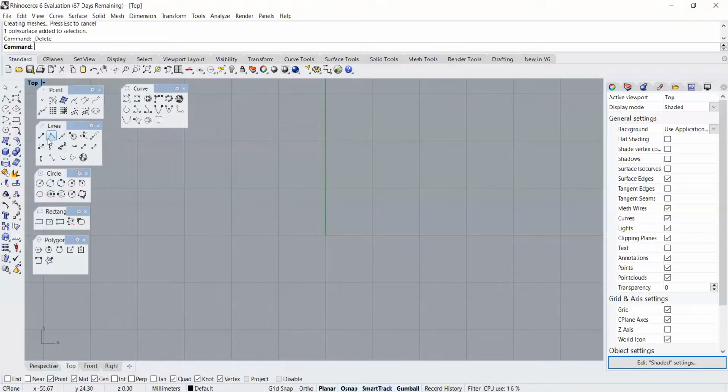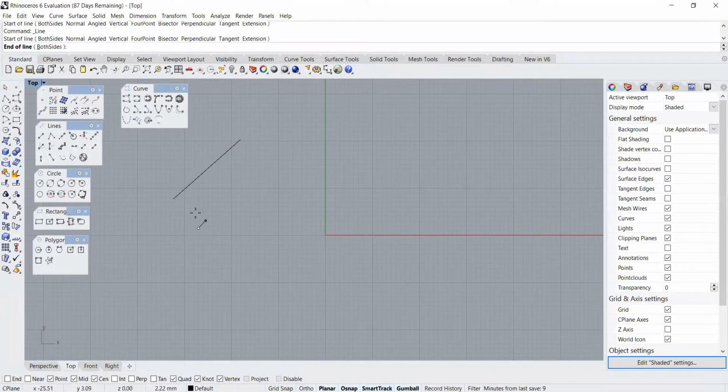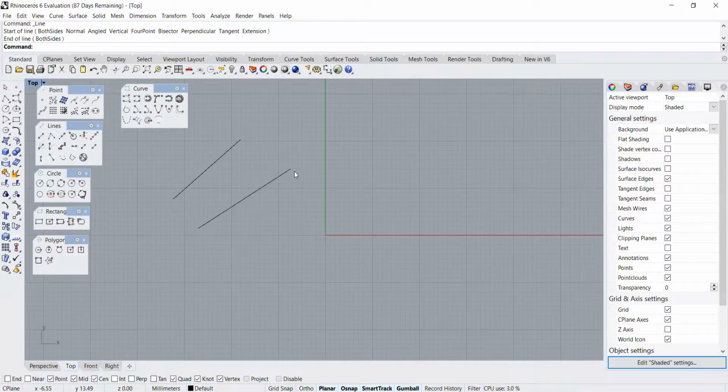So I'll try each and every one out. So it says single line. It's just a segment. So when I do first click, it says end of the line over here. You can see at the command bar, and then click it. Then the line terminates. The command is finished. But when I use the polyline, I say start. It says start of the polyline.